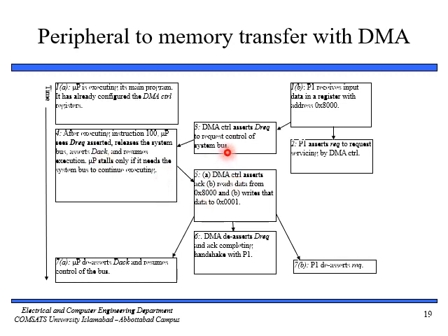So it will assert the signal DACK, meaning that it has seen DREQ and released the system bus, and resumes execution. After releasing the system bus, it will resume the execution of its next instruction. The microprocessor only stalls, it will only go into wait mode, if it requires the system bus for executing.